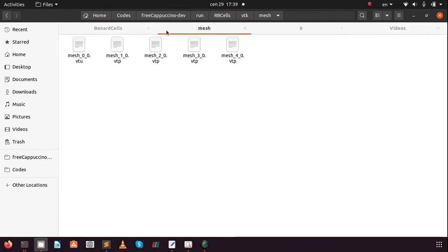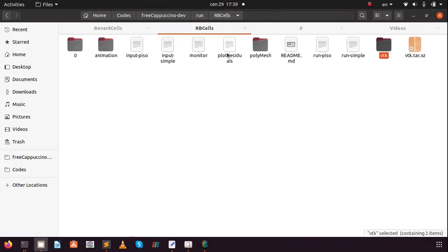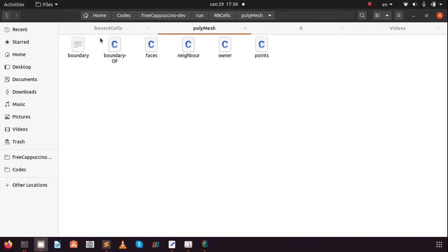Why do I need this? Well, for the simulation itself we don't need cell connectivity data as in OpenFOAM, but for post-processing, for writing VTM, VTU, VTK files for ParaView, because ParaView is cell-based, we need this connectivity data, which is absent in the polyMesh data description.